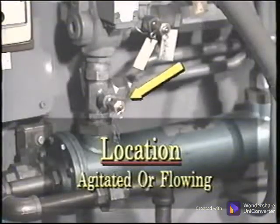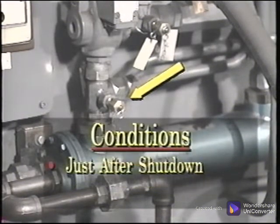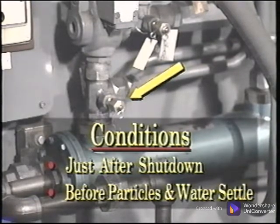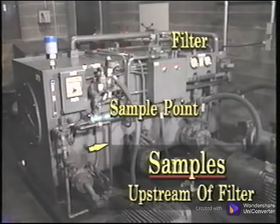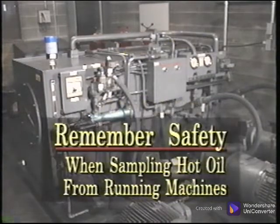In general, oil should be sampled from a location where the oil is well agitated or flowing. Take samples just after the equipment has been shut down or when it's safe while the equipment is operating. It is important to sample before particles and water have time to settle out of the oil. Samples should normally be taken upstream of any filter. If the oil is sampled on the downstream or outlet side of a filter, the debris and particulate contaminants will have been removed by the filter.